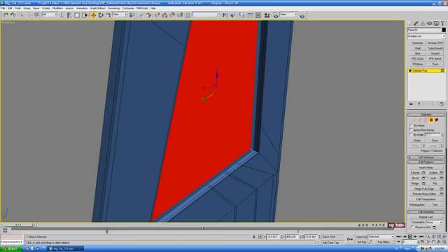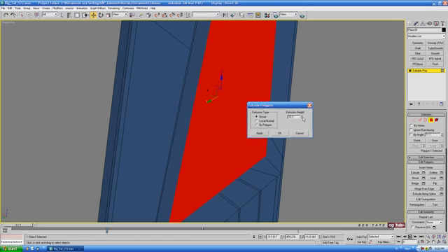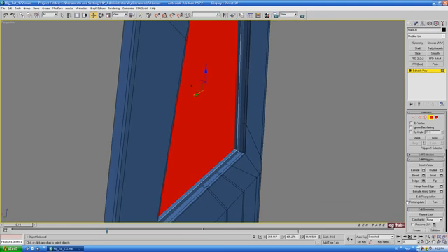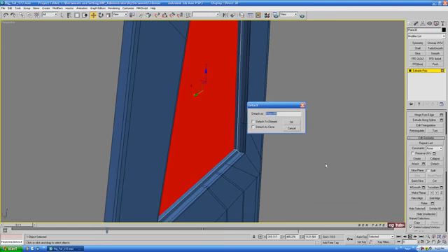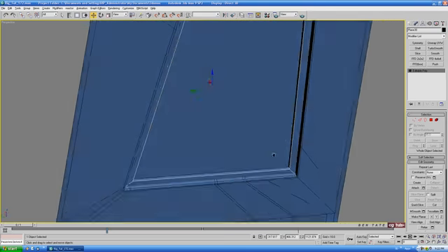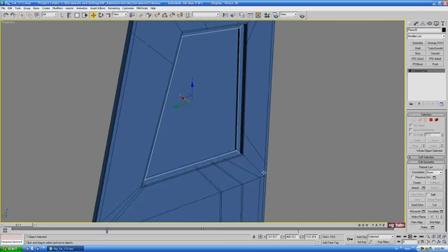And we'll extrude the polygon in, sorry. So let's push that in a bit. Let's do -2.5 again, and okay. And we'll detach the polygon there for the glass later on. So back down, detach, make sure that both boxes are unchecked, and hit OK. And we can just chamfer down some of the edges here.